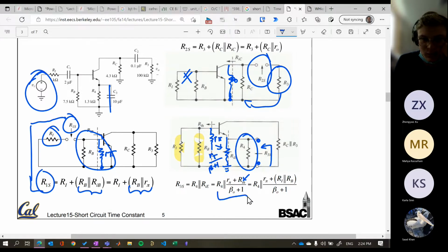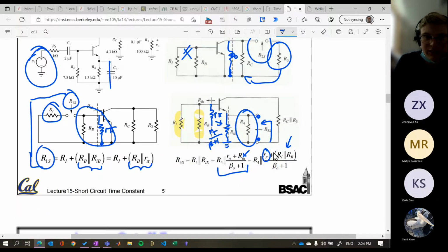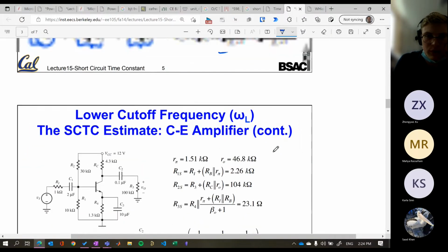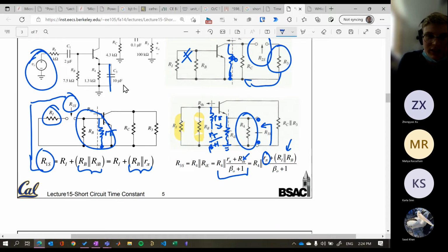So that's exactly what we've done here. And then we can just sub in those different values. So that can be a really handy thing for these annoying bypass capacitors on the emitter. Essentially, those are the ones that look like this, R pi, and then you have RE, and then you have your gm. So you have your gm R pi down here.